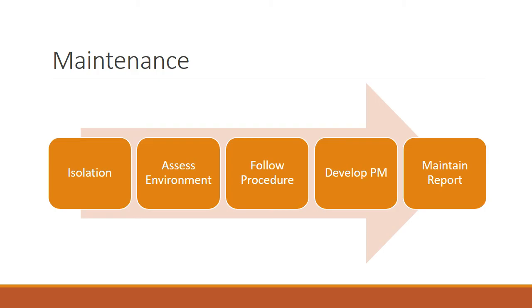Now, nothing is more essential than your safety or your crew's safety. Therefore, learning how to properly isolate your equipment should always be your first concern. Now, determine if your system is radial or double-ended or contains tie breakers. Then look for any backfeed concerns, which might be caused by a generator or someone else testing a transformer downstream that isn't properly separated. This is especially true nowadays, as a lot of people use distributed generation technologies on the customer side of the distribution system. So backfeed is a real concern in this case.